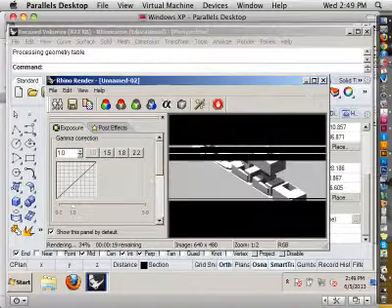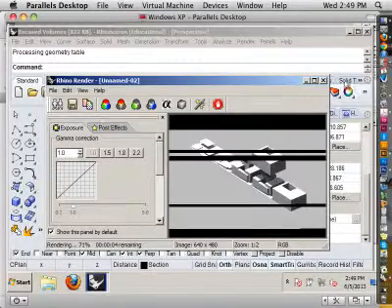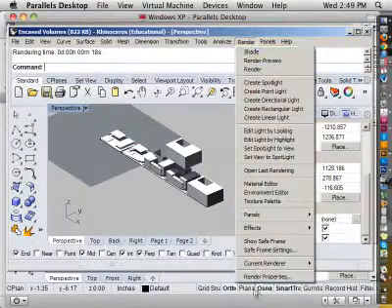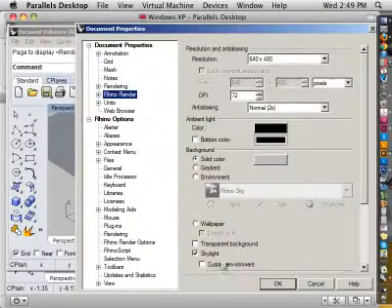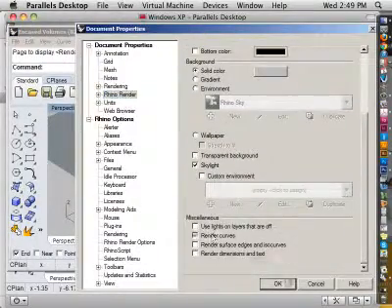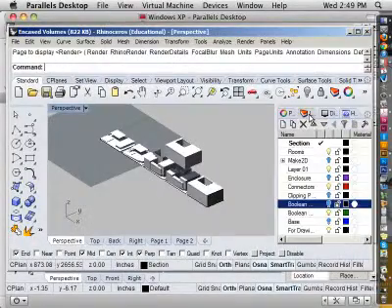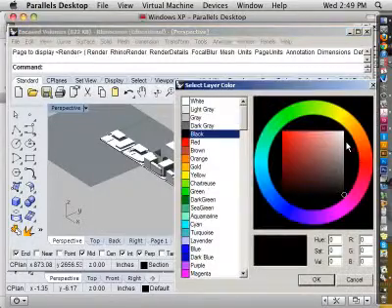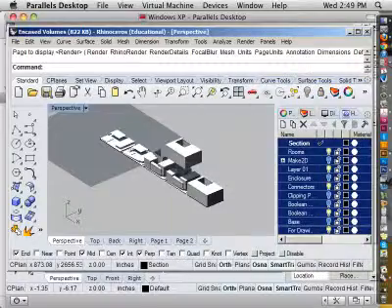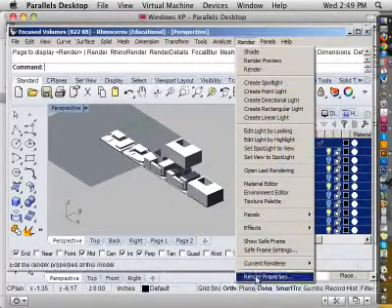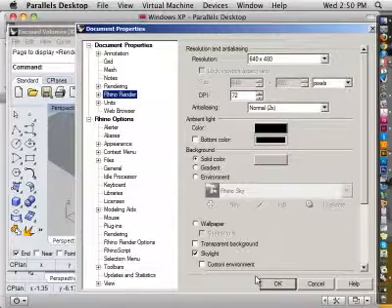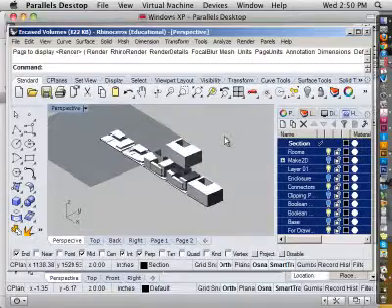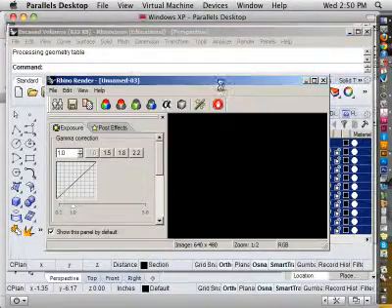So anyway, when you render it and save it, I'll make things a little bit easier for you. Under render properties, turn on your curves, and we're going to turn all of the layers to black, the color to black, so that it'll just render all the curves for us, and you don't have to do a Make 2D on top of everything else. So if you switch all of the layers into black, and then render, it'll draw the lines on it for you.